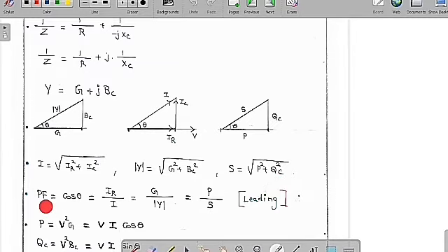And if you want to know the power factor, cos theta is equal to adjacent by hypotenuse, which is G by mod Y, is equal to IR by I, is equal to P by S. So always the current is going to lead the supply voltage, so we say it is a leading power factor. No matter whether you connect the capacitor and resistor in series or in parallel, the power factor of the circuit is always leading, meaning the current is going to lead the supply voltage.